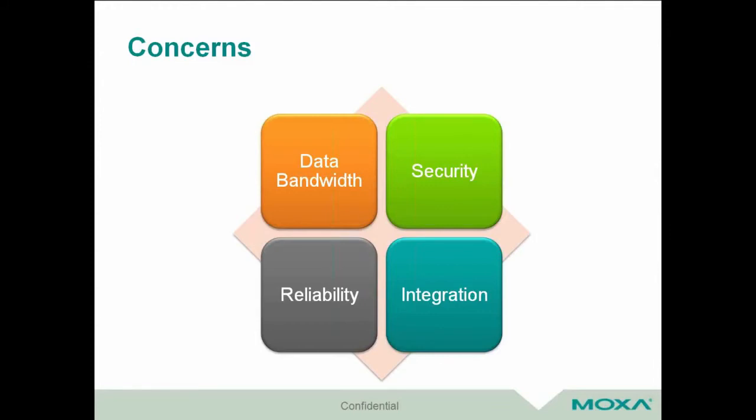And lastly is the integration. If we think about integration, we think about there are legacy devices in those cabinets out on the field. There's serial controllers out there that probably still use RS-232 communications, 485 or 422 communications. And the next question is, how are we going to route that back? We have existing sites that already have this, and how do we expect to pull all that information back without having to make a complete retrofit of that whole environment? There's definitely technologies, and I'll discuss that with you as we proceed on to this presentation.